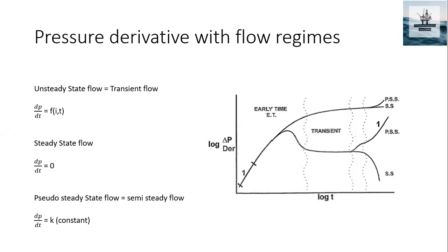With the pressure reduction, reservoir pressure and pressure at the wellbore, like PI and PW, PI will be the same, but PW will be reducing. So with that pressure difference, flow will happen from high pressure to low pressure, that is from reservoir pressure to wellbore pressure. Then it will start entering into your well and move continuously towards the surface.